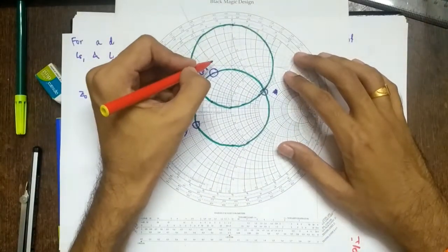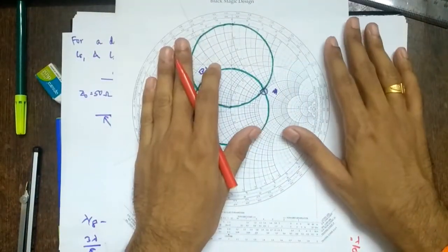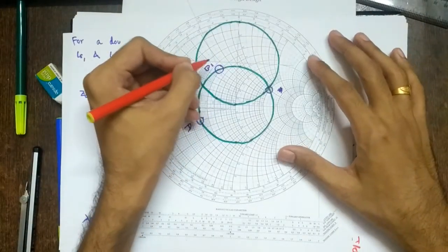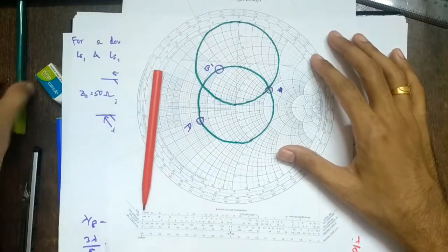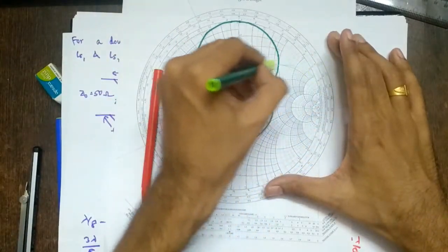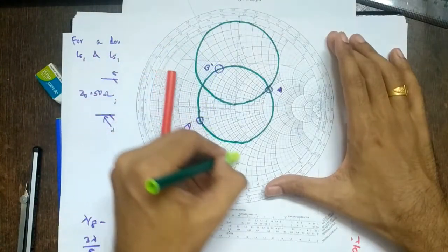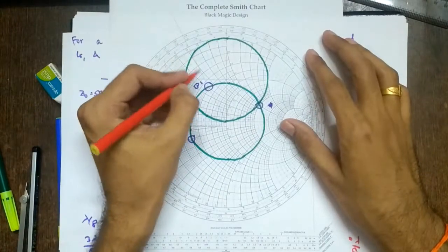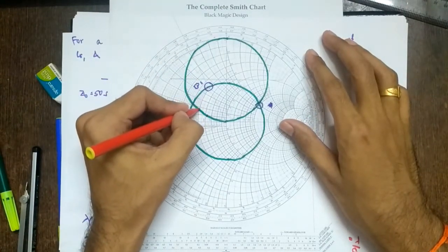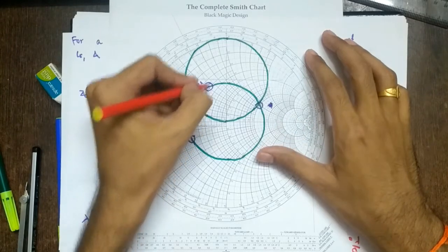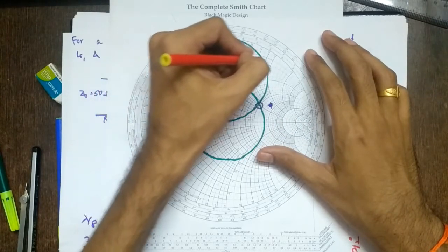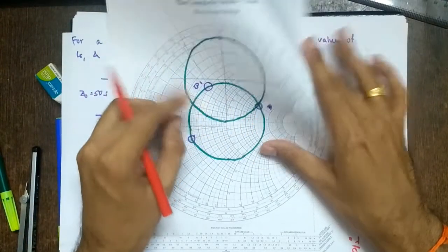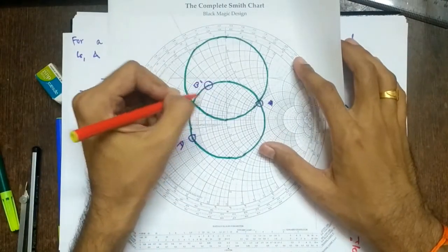So where is the admittance circle? Remember, this is an admittance Smith chart now, that is, we are seeing it 180-degree rotated. So we move on the constant conductance circle. If you have doubts, G equal to 1 is this constant conductance circle. For this point, this will be the constant conductance circle. We have to remember that we have to take the shortest distance. Let's see where we intersect. If we go like this, we intersect here on the G equal to 1 circle. If we go like this, we intersect somewhere over here, so you have to travel a larger distance. So this is the shortest distance. Since the question has asked for the shortest distance, let's take this one.